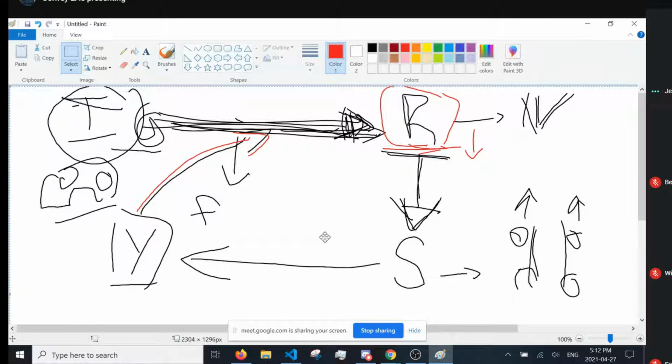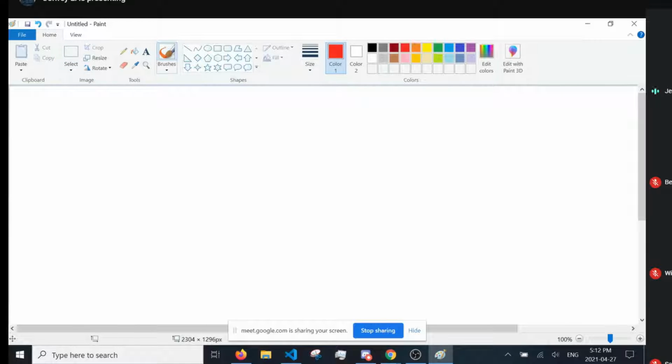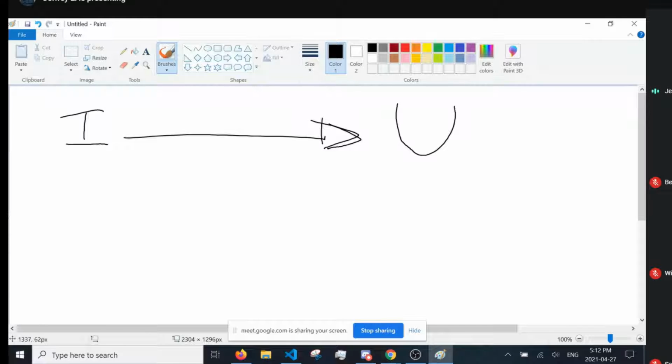So if we have inputs here, I just want to draw again, but be a bit more clear with the full loop system, right? So we have our human inputs over here. And then what we want to get is our robot inputs. Normally we use U to represent our robot inputs. And all you have to remember is that this is just our voltages on our motors, right? And then this step right here is where our control logic lives. So this is our control function F.